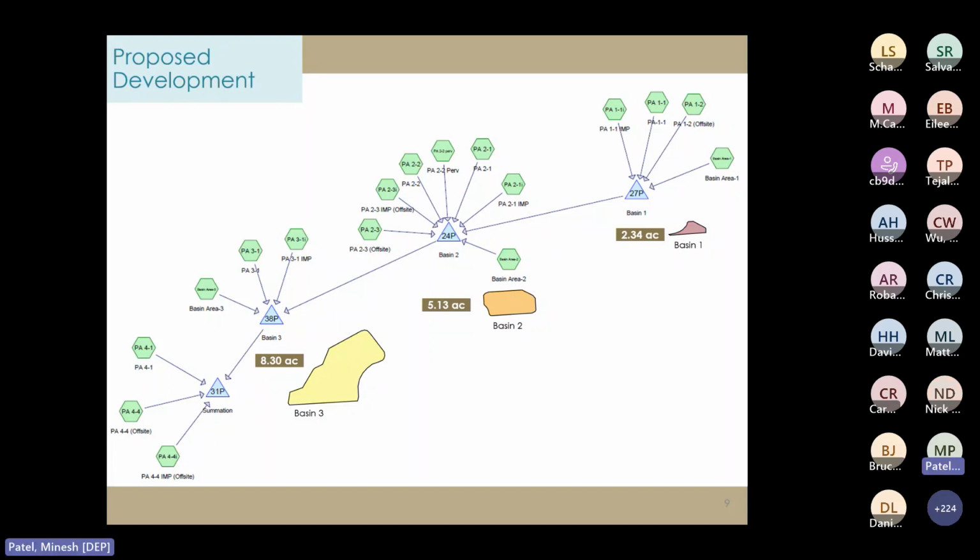The node report shows basin 1 draining to basin 2, and that will then drain to basin 3, such that the contributory drainage areas appear to exceed the 2.5 acre limitation that's established in the rules and in the GI fact sheet. The connections between BMPs is something that has to be checked to determine if this is true.